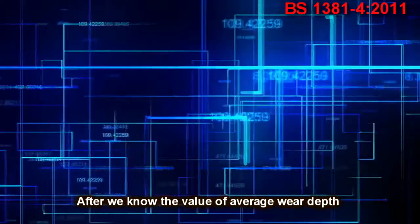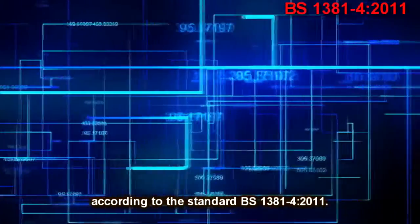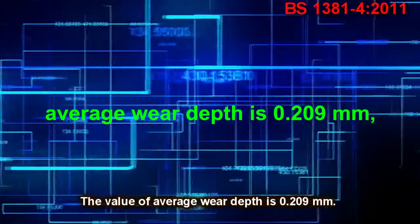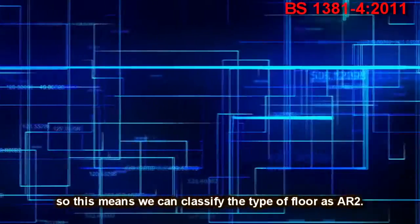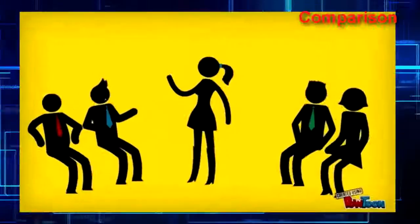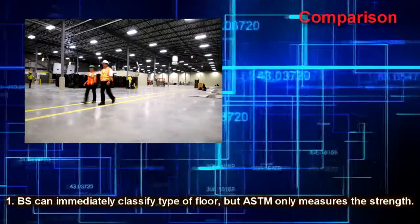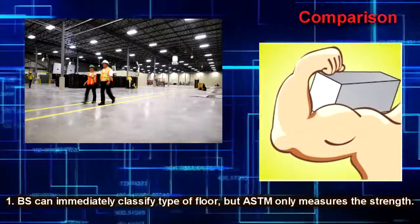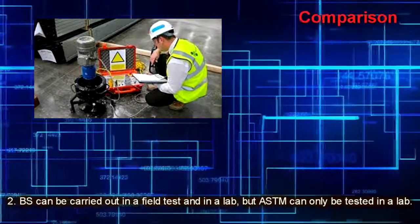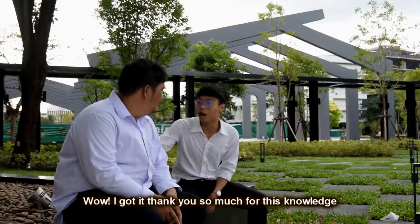After we know the value of average wear depth, we can use this value to classify the type of floor according to the standard BS1381. The value of average wear depth is 0.209 mm, so this means we can classify the type of floor as AR2. From the two testing methods we can see the main differences between the two are: 1. BS can immediately classify type of floor, but ASTM only measures the strength. 2. BS can be carried out in a field test and in a lab, but ASTM can only be tested in a lab.